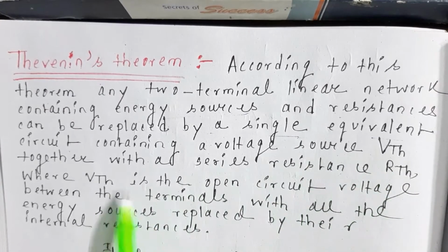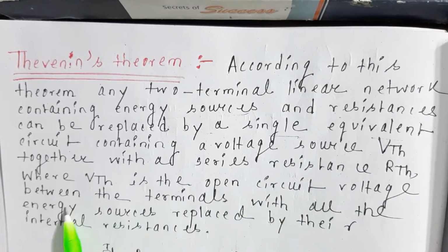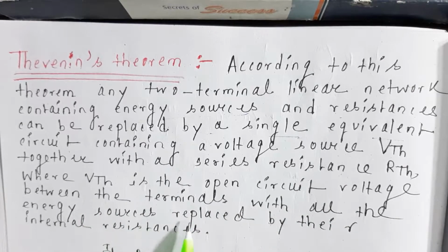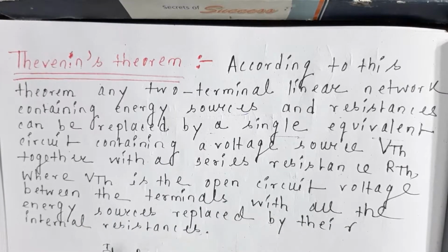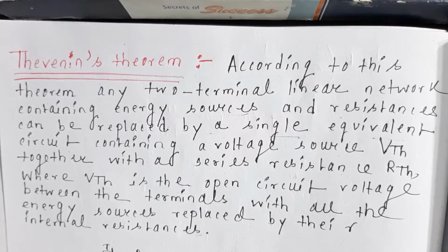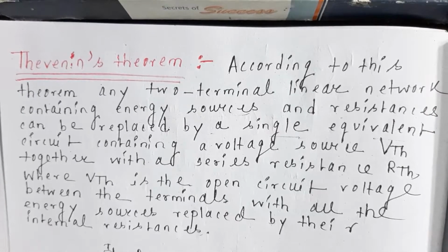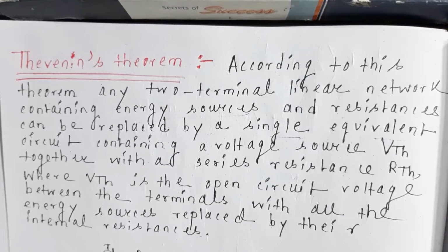This VTH is the open circuit voltage between the terminals with all the energy sources replaced by their internal resistances. So let us understand this even more clearly with the help of a circuit.